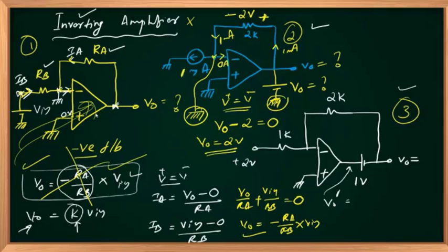Any issues? Applying KVL, writing Ohm's law, taking the closed loop, starting from ground, ending at ground, equating to 0. Then my unknown, V out, equal to 0. I have applied V plus equal to V minus first, then my KVL along with the input current to the op-amp equal to 0. Any other issues, any problems? Okay or no? Right.